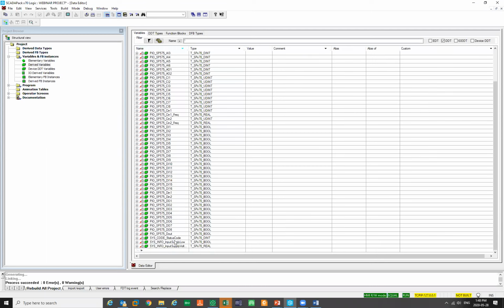What about the RTU temperature? It was not available because in the logic editor I had not set the data type to one of these logic types. By not being assigned a logic type, it does not appear in this list. If we went back and assigned that, it would appear in the list here, and we could use that in the code. So that's how you make sure that objects are linked to logic or not, as the case may be.